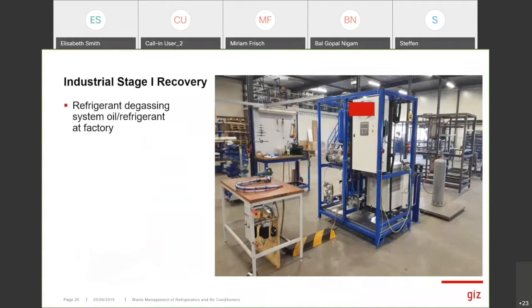It is necessary to have a deep cooling chamber for temperatures down to approximately minus 35 degrees Celsius for the removing of the non-condensable gases from the received refrigerant. And on the other hand, it is a pneumatic system for the refrigerant and oil recovery system.